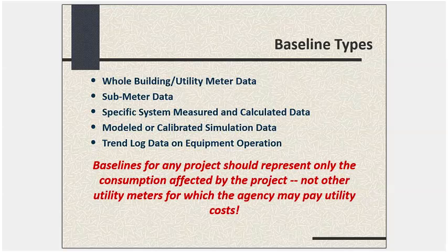Except, when we looked at this on the airports project, there were maybe 80 plus meters that were affected by the project, but there were another 20 or 30 meters that weren't part of the project. But when somebody started to look at analyzing utility bills, they included those other 20 or 30 meters. Well, that makes your comparison not really that accurate because you're looking at a bunch of meters that are not really affected by the project. So, sort of basic, but important to look at.